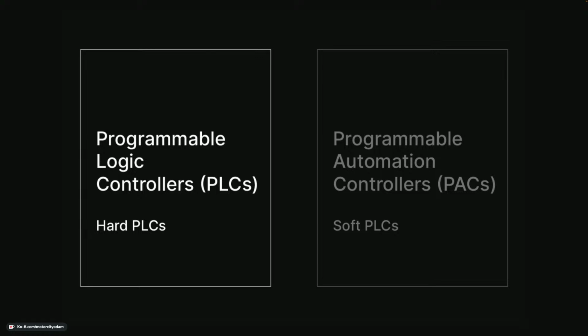And so that is a distinct entity from a programmable logic controller, which we are going to stay on for quite some time. A programmable logic controller is a lot simpler. They're dedicated hardware that supports usually a fixed set of programming languages, and they're really only dedicated to one thing. Now there's been some overlap in recent years where programmable logic controllers have gained some motion control functionalities, and we will dive into that later. But for all intents and purposes, we will be sticking with the simpler, dedicated, domain-specific programmable logic controller, and then we'll graduate to the right side in time.